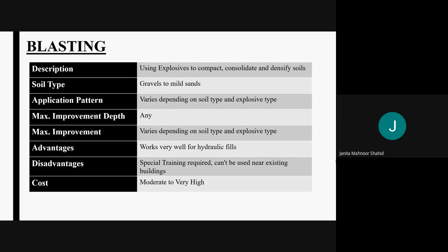The energy released by explosions creates compressive radial stresses in the soil, which are generated as the shock waves approach towards the source, and then tensile stresses are produced as they pass. The resulting cyclic stress increases the pore pressure, and effective stresses are gradually reduced. As pore water pressure dissipates, the grains of the soil rearrange themselves into a denser and more stable configuration.